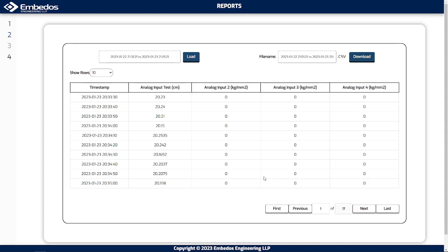peripheral data like digital inputs or digital output or analog output or state change operations. Now this also has an option wherein you can customize this to log a certain data on occurrence of certain events, and all of this can be made completely customizable based on the application. So the analog and digital input data can result into generating some sort of digital or analog output or some message logging into this table, and all of that can again be downloaded as a CSV file from the exact same utility.